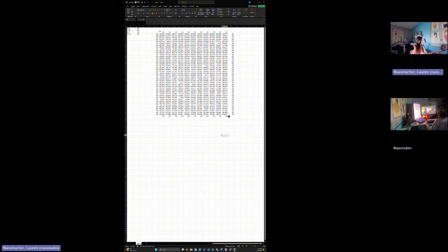Let's take this and spread it throughout the entire grid. And now we have a fully functional Excel sheet that shows how our temperature diffuses across a grid. And you'll notice that if you look at any part of this grid, the average of the block below, above, to the left, and to the right is equivalent to the temperature in that spot.